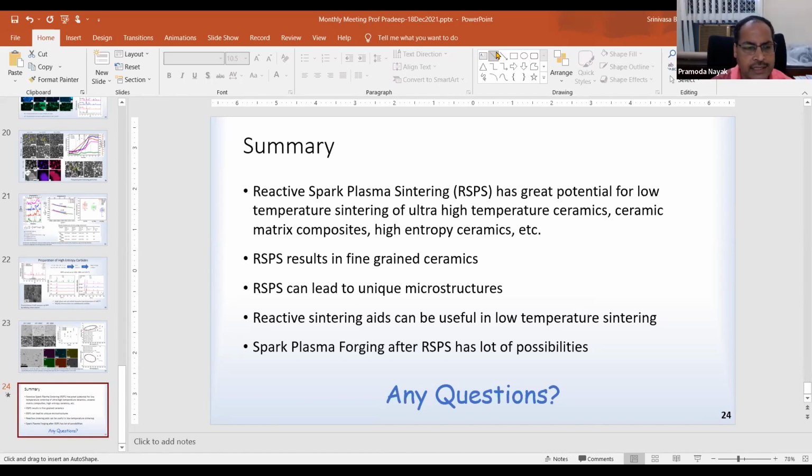And how do you decide the pressure and temperature for a particular sintering? Take a phase diagram, pressure versus temperature, of that system, and then we definitely look at the melting point. We typically have data available for hot pressing, and we generally use temperatures 200 to 400 degrees lower than that, because we know it will work. But it is always trial and error to obtain the optimum parameters.